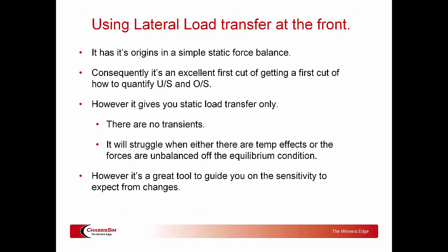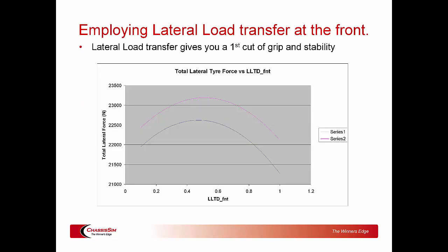Now, the thing about using lateral load transfer at the front, yes, it's all based on static approximation. So it's a first cut. This is not the be-all and end-all that you will sacrifice everything on the altar of car setup to. However, what it does do is give you that first cut of what the grip is going to do and how the stability index will go for a given lateral load transfer distribution. So this is your first port of call to trying to nut out what a setup will do. And one of the great things about this is that it gives you the ability to plot grip versus lateral load transfer distribution. I've done that here for 2 different tire compounds.